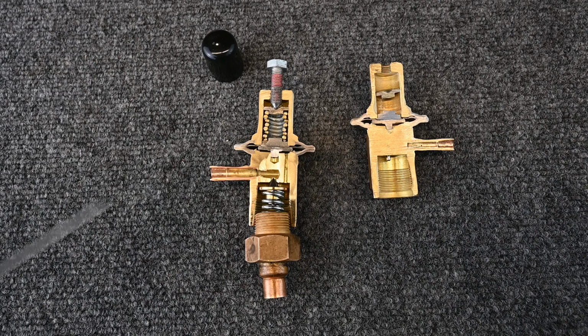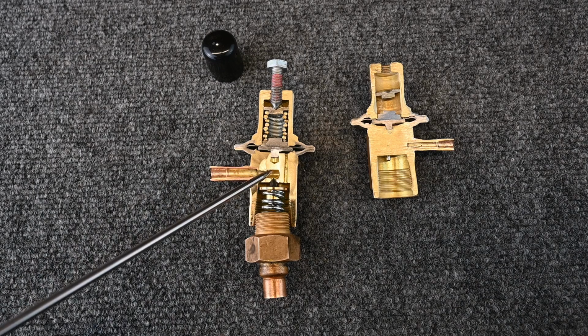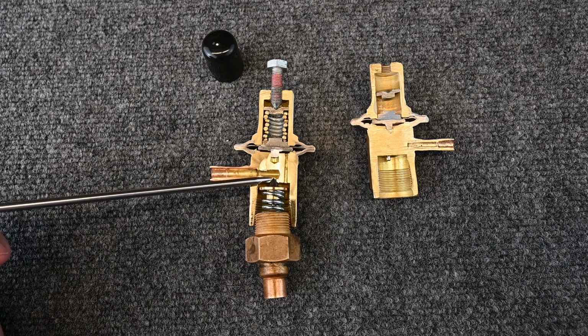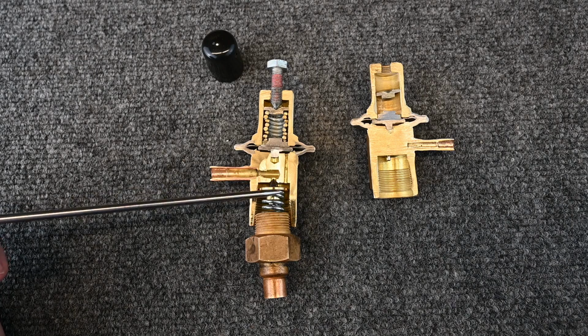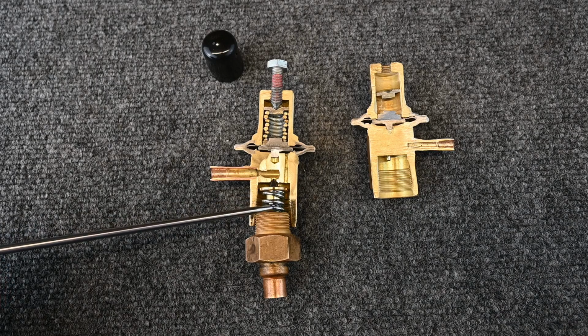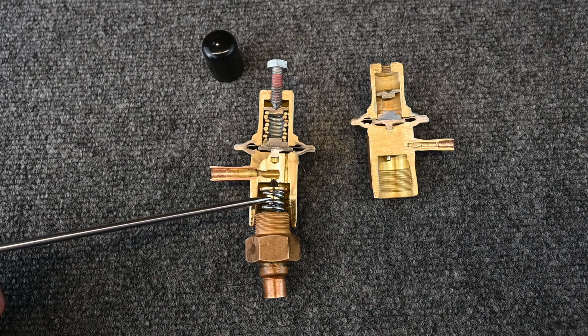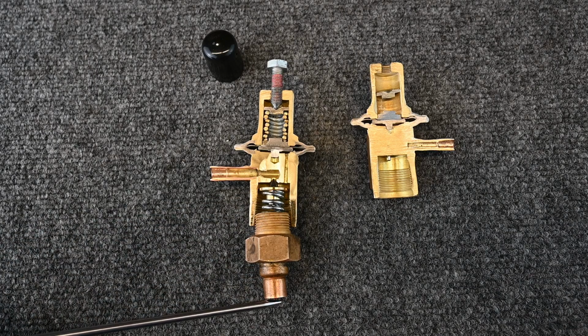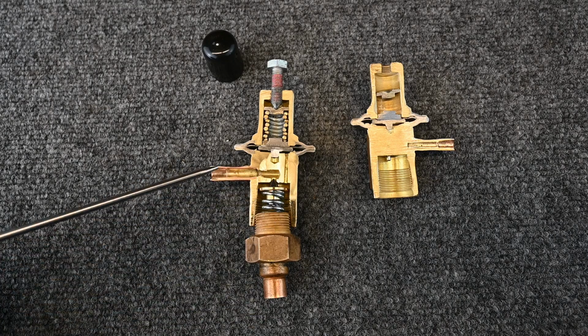In our simplest form, liquid refrigerant comes in through our liquid line, and right in this chamber there's going to be a hole and another fitting right here. What's happening is that is our metering device. That is what's metering the refrigerant. The size of this hole is going to change because there's a little cone right here that shoves into that hole. And as this plate moves back and forth, it adjusts how much refrigerant is coming through this hole. Here is our low pressure side where we have our pressure drop. And from there we continue on out the bottom, and that's going to our evaporator coil. So our metering device is in its simplest form right there.